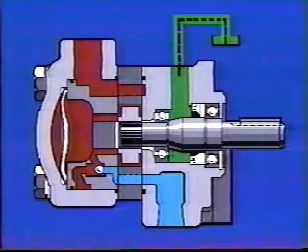Because of the reversibility of a motor, leakage oil that collects in the shaft chamber has to be drained externally. We cannot drain the unit internally because at one time or another each port is pressurized.